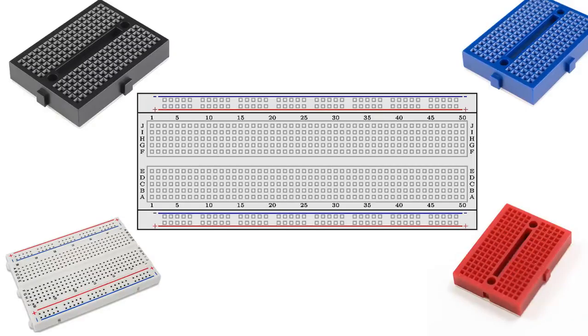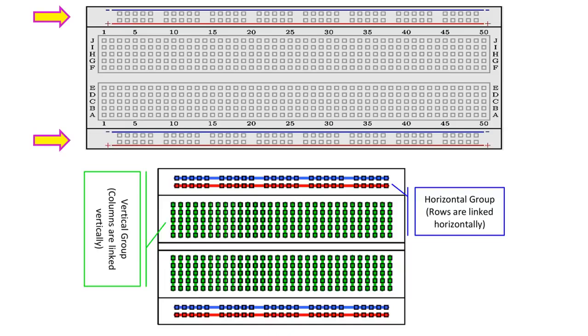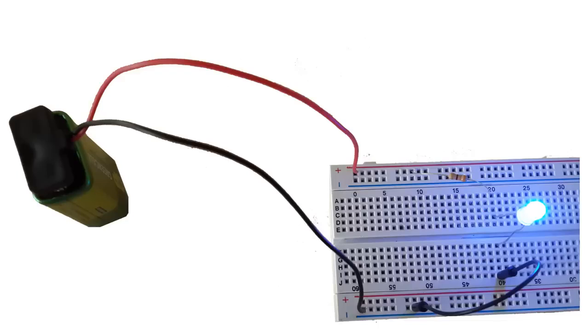Step 13. Breadboards. Breadboards are special boards for prototyping electronics. They are covered with a grid of holes which are split into electrically continuous rows. In the central part, there are 2 columns of rows that are side by side. This is designed to allow you to insert an integrated circuit into the center. After it is inserted, each pin of the integrated circuit will have a row of electrically continuous holes connected to it. In this way, you can quickly build a circuit without having to do any soldering or twisting wires together.